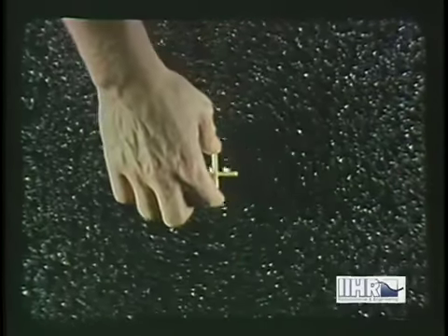However, if the velocity varies inversely with the radius, as it tends to do in the field of flow surrounding a vortex filament, whether above a drain or in a tornado, a line or stick in the tangential direction will tend to rotate in the opposite sense from one in the normal, but at the same rate. Two perpendicular sticks fastened together will then not rotate at all. Such flow is called irrotational. The central filament itself, of course, is highly rotational.